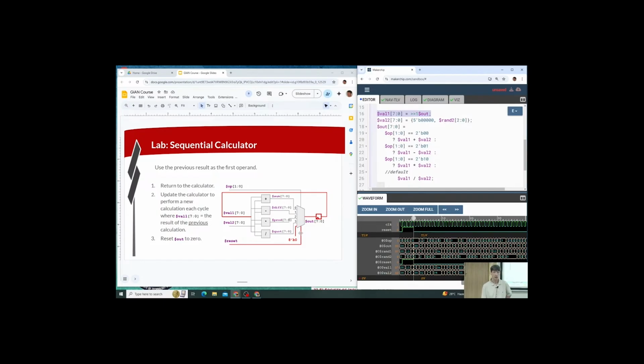Reset needs to be highest priority, right? If it's not highest priority, there's no guarantee that we actually reset our circuit. Highest priority means it has to be at the top of our chained ternary operator. So we need a case for reset. If it's reset, we want to use an 8-bit value 0. Okay, so again, it's that simple. We just need an extra case in our mux.